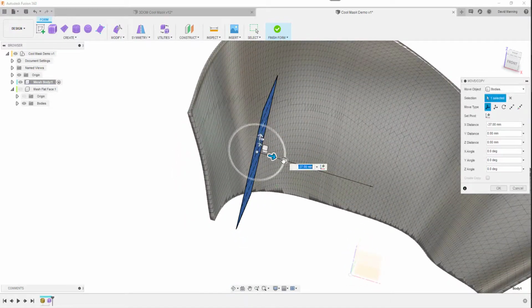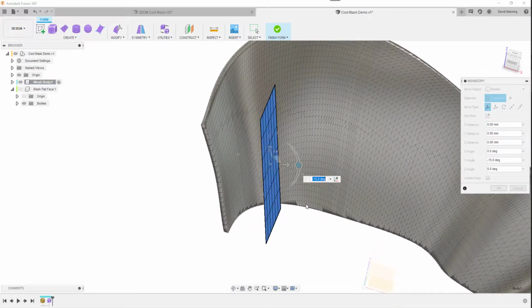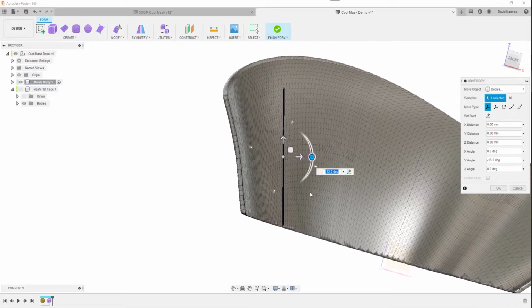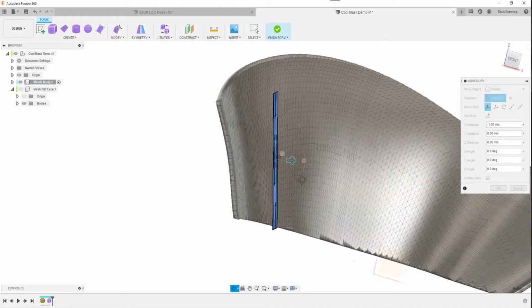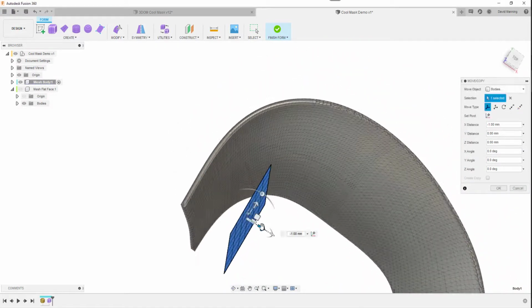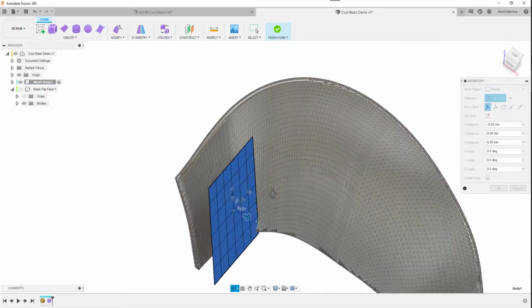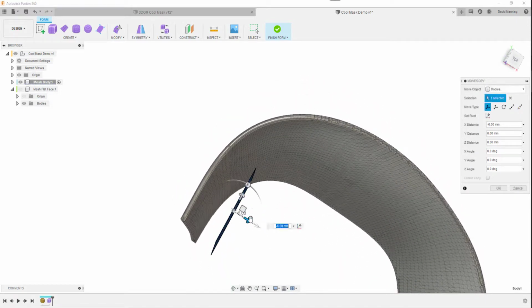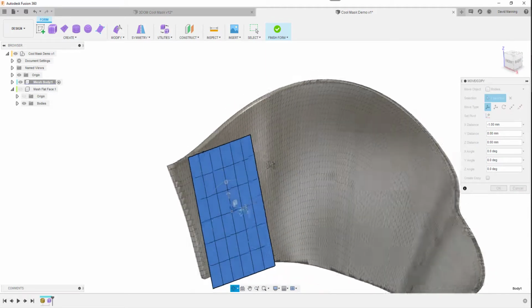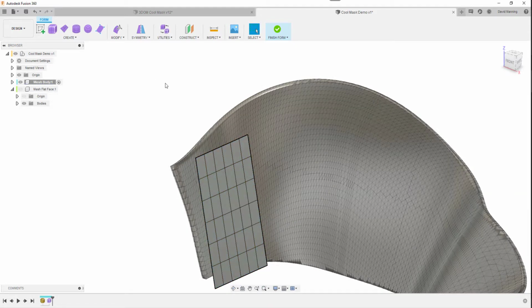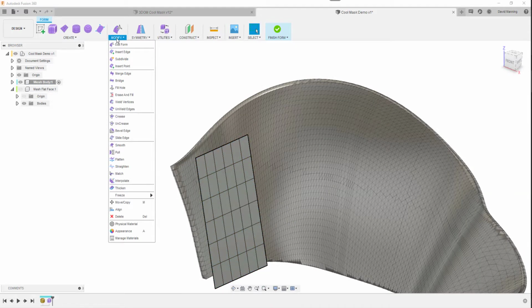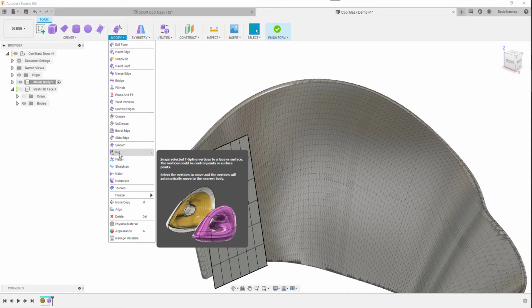in place. And I can also do things like the angles and sort of align it, but of course the mesh we're moving to is not a flat plane. The thing I'm watching for is I don't want to occlude there. You see the bottom corner, it's now projecting into the mesh. I'm trying to avoid that, so maybe we just do a bit of an angle on that. That's fine. I'm not too concerned about being pedantic about it because I'm going to use a funky little tool Fusion has here where we can pull an object to a surface.